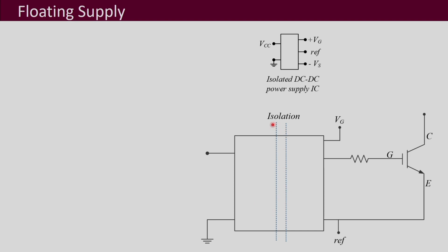This is your gate driver, which in case of an optocoupler based gate driver provides the optical isolation, plus you will be having the totem pole, and then this is your gate emitter region, and this IC will be given the supply using a floating source whose reference will be this emitter region.